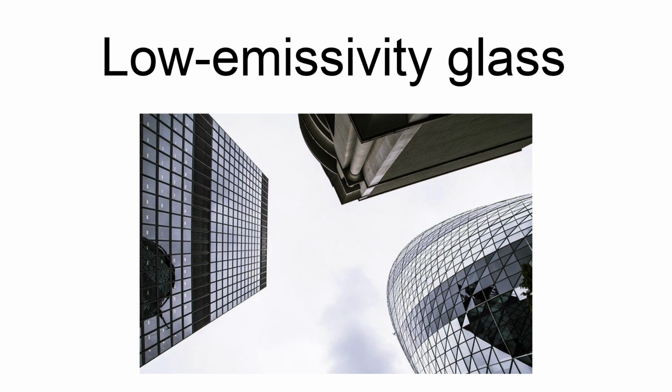Glass coated with a low-emissivity substance can reflect radiant infrared energy, encouraging radiant heat to remain on the same side of the glass from which it originated, while letting visible light pass. This often results in more efficient windows because radiant heat originating from indoors in winter is reflected back inside, while infrared heat radiation from the sun during summer is reflected away, keeping it cooler inside.